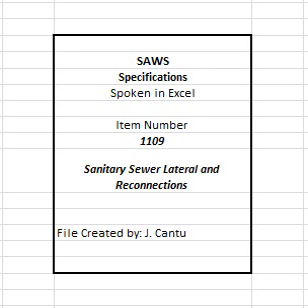D. For pipe-bursted sanitary sewer mains, allow liner to normalize to ambient temperature and recover from imposed stretch. For cured in-place liners, verify that liner is completely cured. E. For new parallel and replacement sanitary sewer mains, complete testing and acceptance of downstream sewers as applicable.